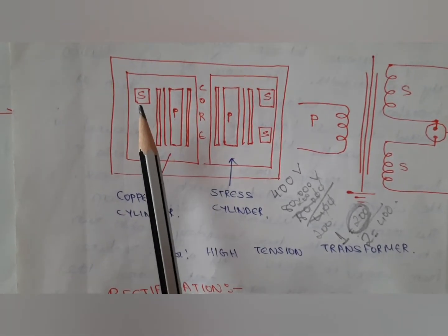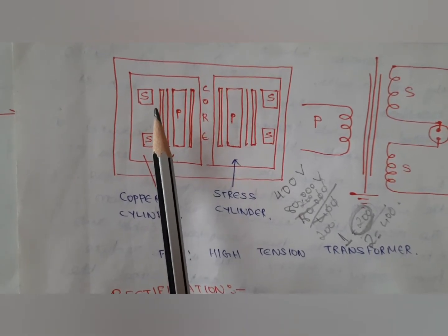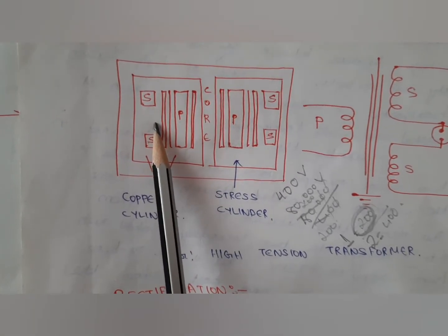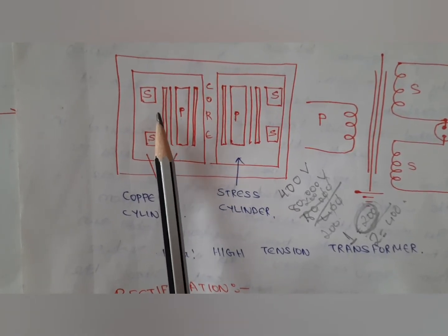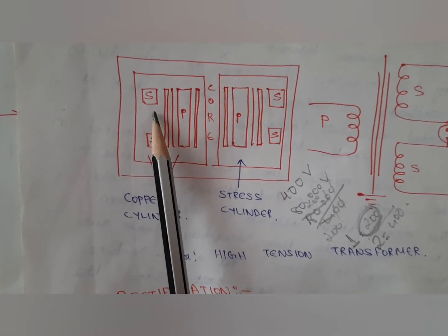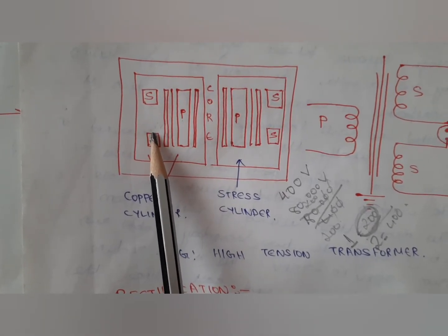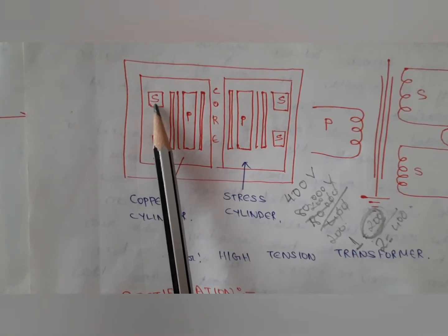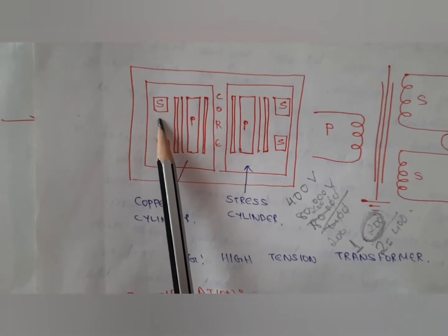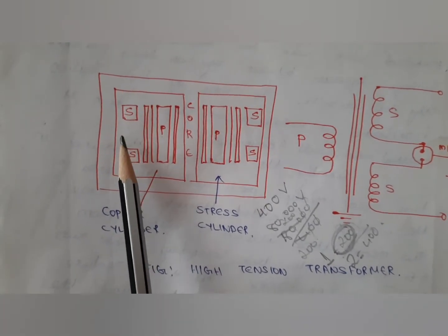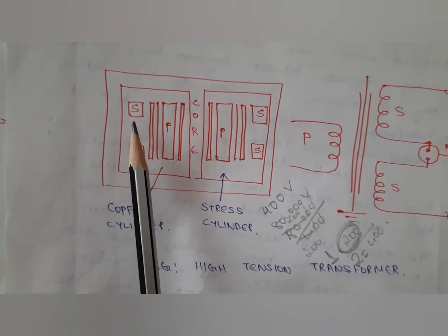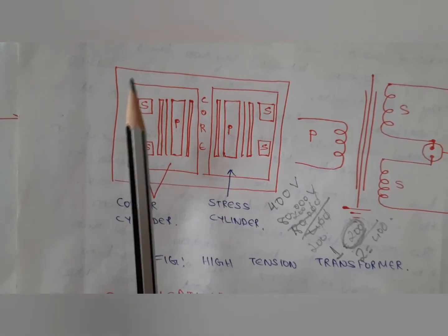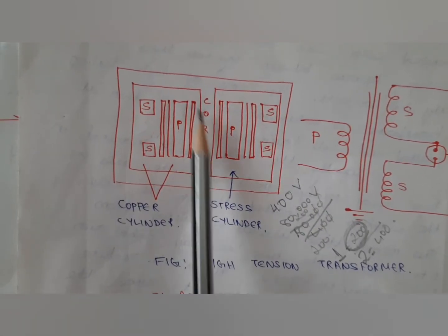This thin copper wire is coated with insulating varnish. The wire is wound on an insulated cylinder which is placed over the primary winding. The layers of the secondary coil are separated by a thin paper of wax which provides electrical insulation. The entire arrangement is placed in a shell type core.